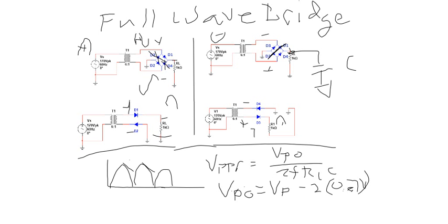That's because no matter which one of those circuits is active, whether it's a positive half cycle or a negative half cycle, only two diodes are turned on at a time, but you do have to account for both of them. So you would have both diode drops you have to deal with there.